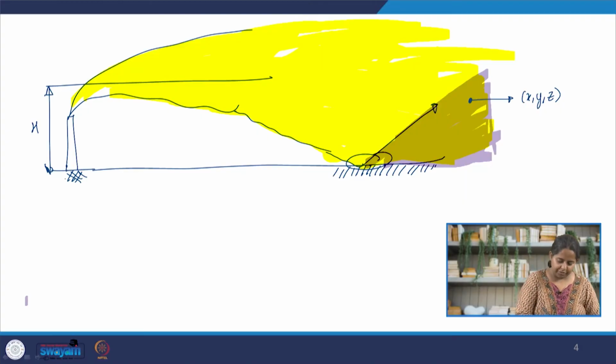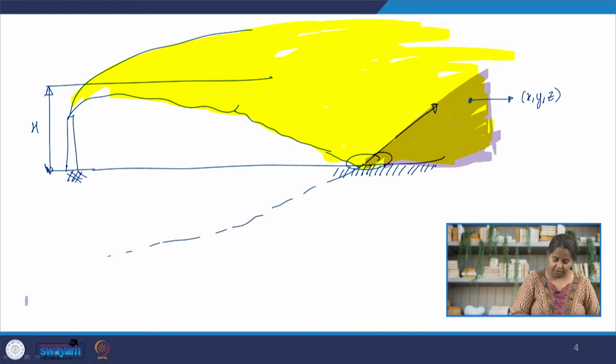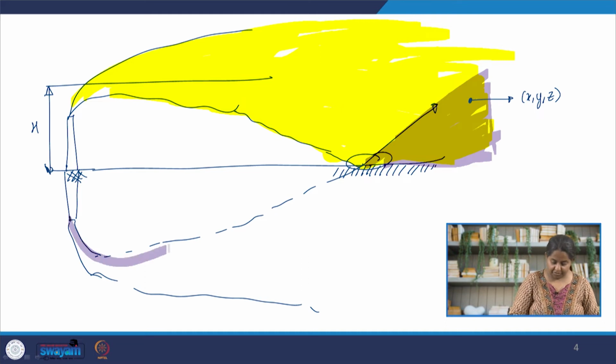Alright students, I hope you figured out how to go about this. If you didn't, don't worry, no pressure. The virtual plume, we are going to again have a virtual plume. So earth is acting like a mirror, right? Earlier the obstruction was acting like a mirror, so there was a virtual chimney on the other side of the obstruction. Now here the earth is acting like a mirror, so we are going to have a virtual chimney on the other side of the mirror, which is the earth in this case. So apologize for my not so perfect drawing. My virtual chimney is not going to be an exact copy of the original, obviously. So this is the virtual smoke.